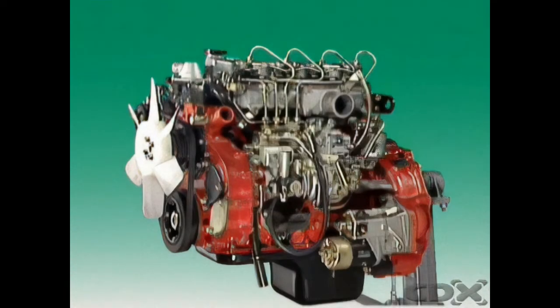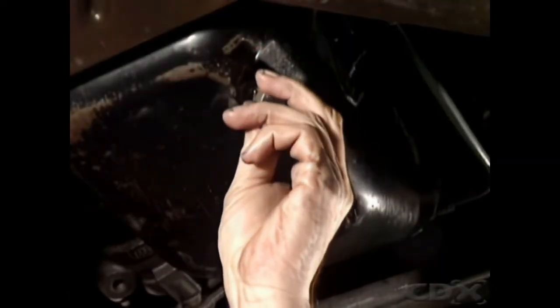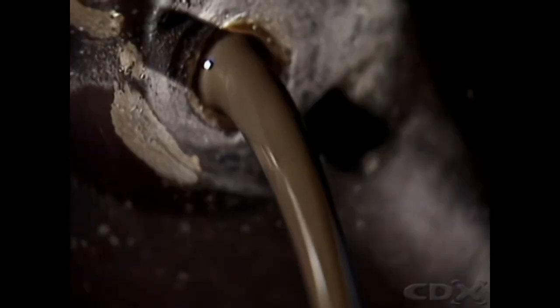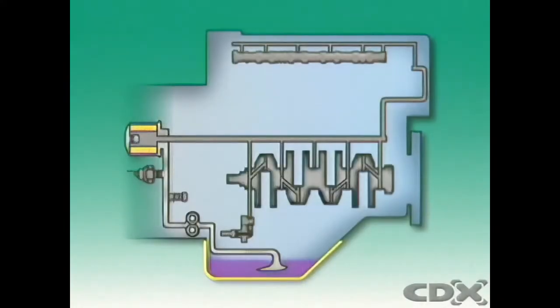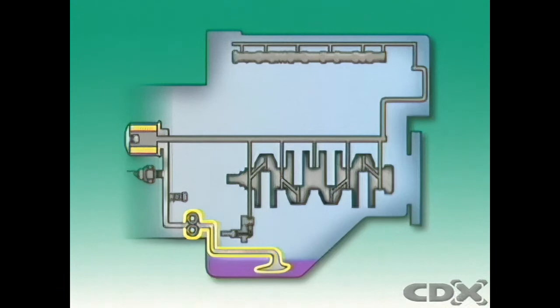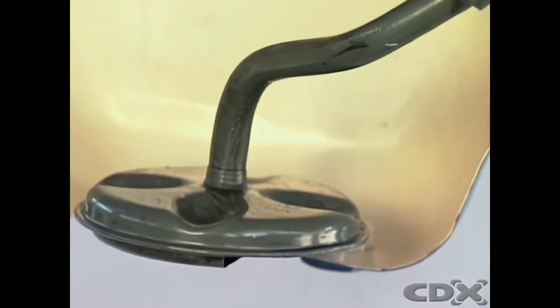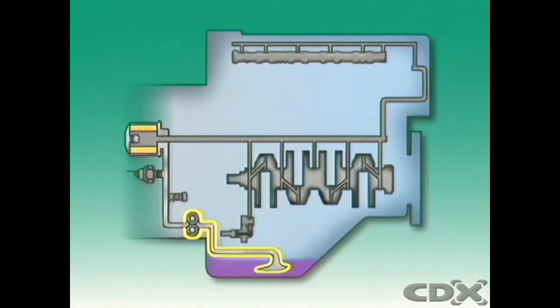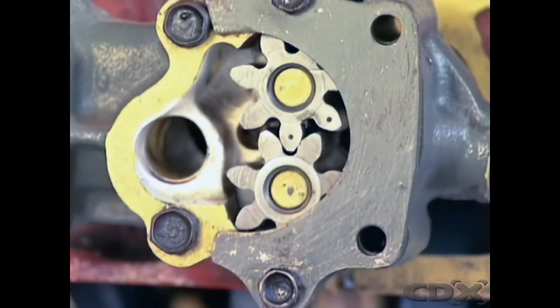The sump is bolted to the engine under the crankcase. It is a reservoir or storage container for the engine lubricating oil and a collector for oil returning from the engine lubricating system. The sump can be formed as a thin sheet metal pressing and shaped to ensure that oil will return to its deepest section. The oil pickup tube and strainer are located in this deep section to ensure they stay submerged in oil and to prevent air being drawn into the oil pump.